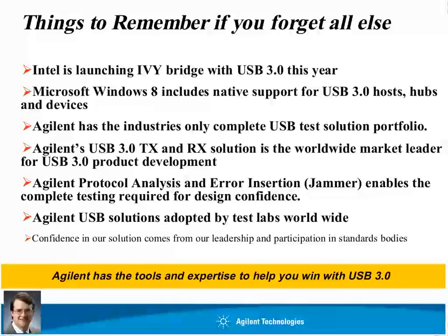Next question was, what are the scope bandwidth requirements for USB 3? It's similar to PCI Express Gen 2 signal rates. Well, it's exactly the same, and the minimum scope bandwidth for that is 12 gigahertz.